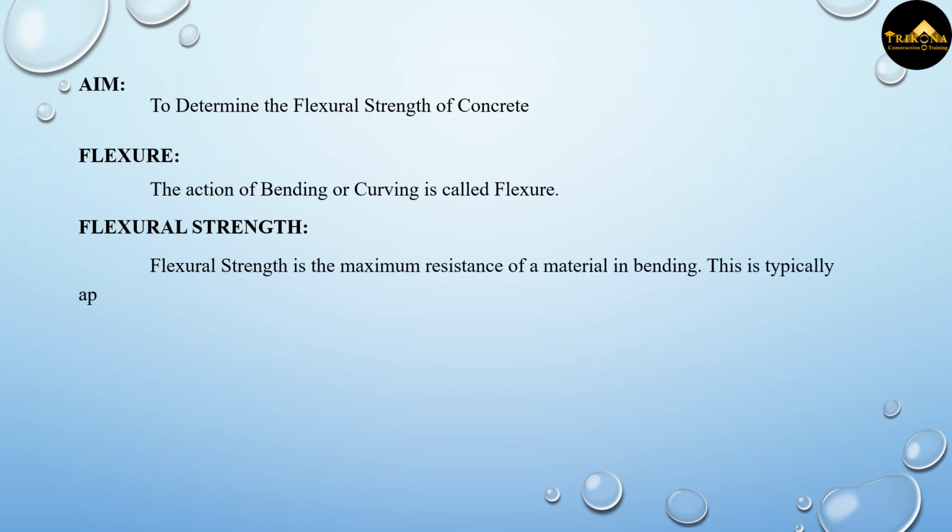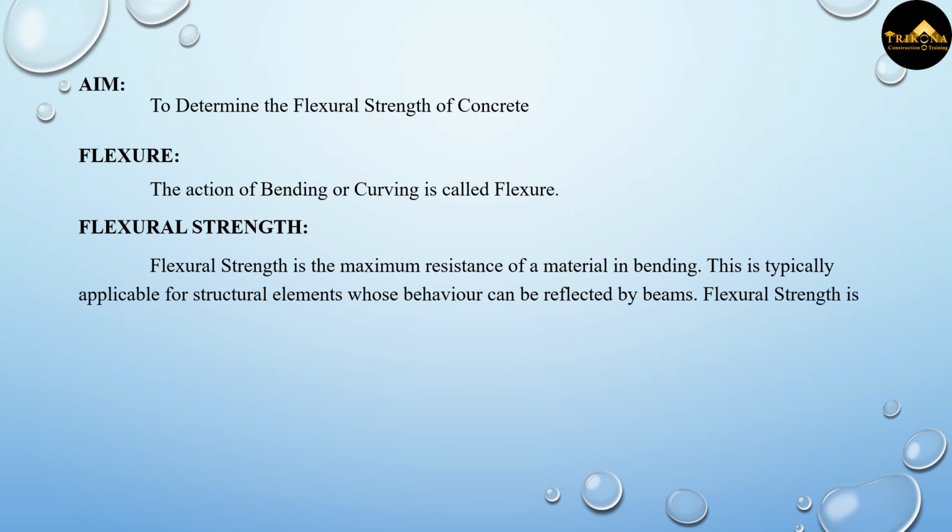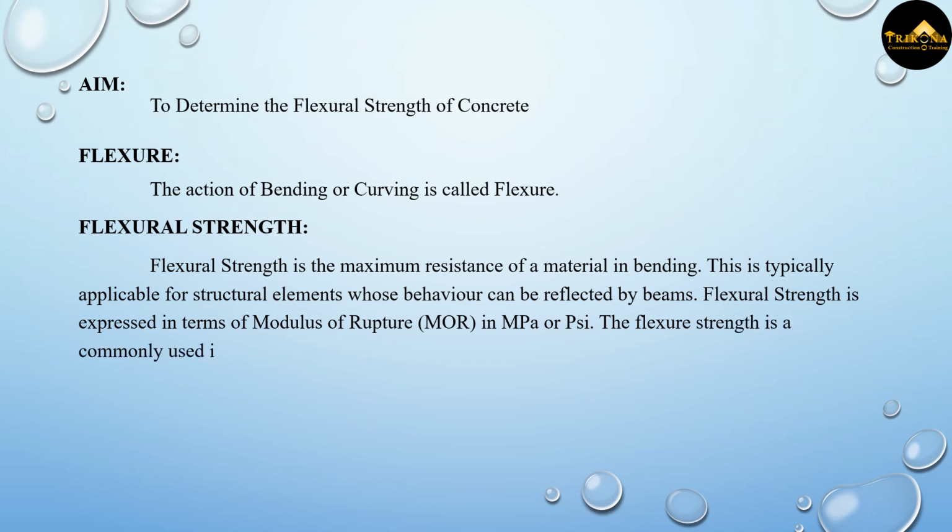This is typically applicable for structural elements whose behavior can be reflected by beams. Flexural strength is expressed in terms of modulus of rupture in megapascals or pascals. The flexural strength is commonly used in the design of rigid pavements.